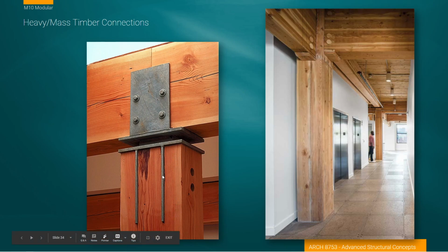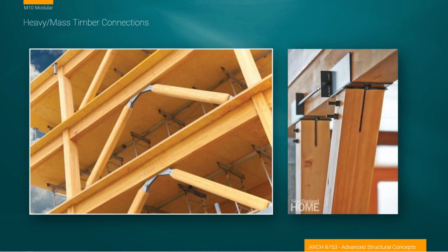Notice these long slotted insertions into the timber to take the loads and spread them out away from the contact point. The bolting through the heavy timber to connect it. In this case, we have what looks like pin connections. These may be bolted connections with things that appear to be pins over the top of them. It also could be a wooden pin connection, but I tend to doubt it because of the configuration here.